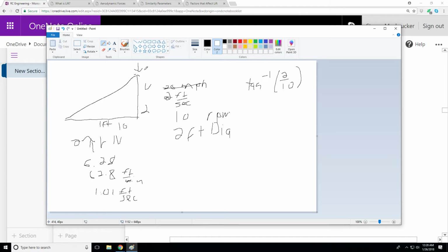So it's basically saying how much of the air is going to help generate thrust at the rest of the blade than how I'm actually rotating. So towards the end of the blade, when you're generating the most thrust, you're spinning way faster than the air is hitting it, because the air does not change at 2 feet per second. So RPM does not change and wind speed does not change. So as it's hitting your plane, that airspeed is not changing, RPM is not changing, but your speed along the radius of the propeller is changing.